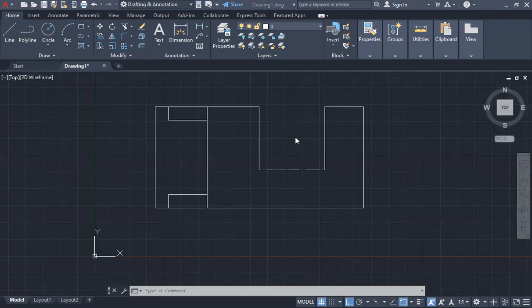Okay, so quickly, just how I drew this shape, if you were a bit confused as to what line lengths I'm using. I used my equation, 75 divided by 2 plus 113 to find this length. The total height here is 75 from the drawing, and across is 28. From this point down, I used another equation, 75 minus 28 to find this point. And then I started another line over here, went up 75, across 75, and then down again using that equation, 75 minus 28, and then just join these 2 points.